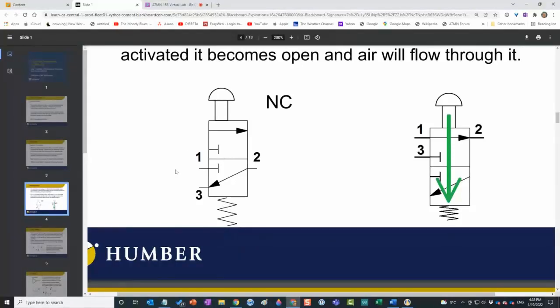When I press the button, this configuration becomes the active configuration. Now watch this. Imagine that you hooked up pressurized air to port number 1, this little line coming out here. Pressurized air would come in and get blocked by this T. It would go nowhere. Now, there's a connection here with port 2 that goes over to port 3, so the air can flow here. If I had pressurized air here, it would flow this way and come out port 3. Okay, well that's fine.